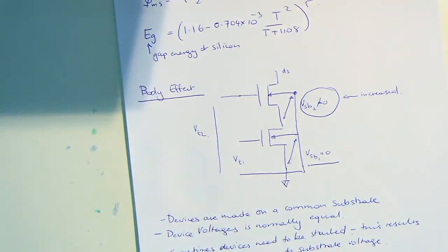Okay. So then you can actually work out what your maximum power is. If you work that out in dBm, it will be a little bit less than that, because you've also got a threshold voltage and whatever, right? It's probably going to be half a volt squared over 50 ohms. That's the maximum you can get out. So therefore, you don't get a lot of dBm out, right? A lot of watts, right?